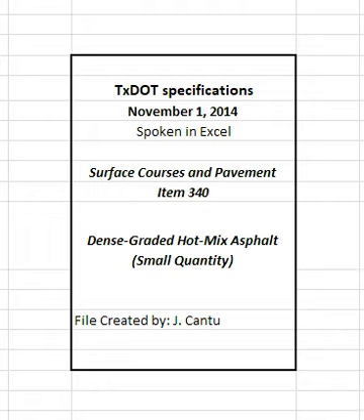Table 5. Allowable substitute PG binders and maximum recycled binder ratios. See table in specifications. 1. Combined recycled binder from RAP and RAS. 2. Use no more than 20% recycled binder when using this originally specified PG binder. 3. WMA as defined in Section 340.2.6.2, Warm Mix Asphalt, WMA, DOT. 4. When used with WMA, this originally specified PG binder is allowed for use at the maximum recycled binder ratios shown in this table.